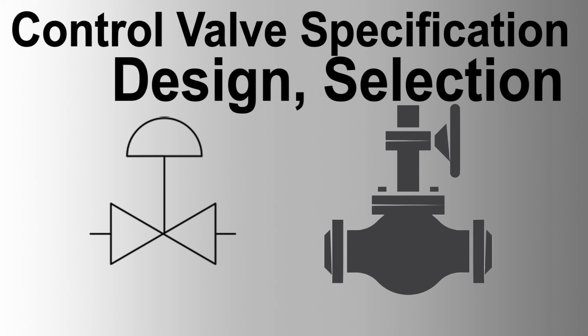4.4 Ball valves. Applications: high turn down, suitable for abrasive services with ceramic materials. Sizes: 10 millimeters to 500 millimeters. Characteristics: turn down up to 500 to 1 for V-ported valves. Limitations: not recommended for slurries, high-pressure drops.